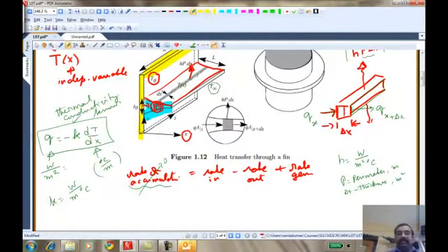On the right hand side, let's look at rate of generation. Is there any heat being generated inside the control volume? The control volume is this now. There is no mechanism for heat generation here. Where are the situations where you could have a mechanism? Suppose this were a catalyst pellet in a reactor. There is a reaction taking place. There is heat of reaction. And you are interested in predicting the temperature distribution in a catalyst pellet. You will have to worry about that.